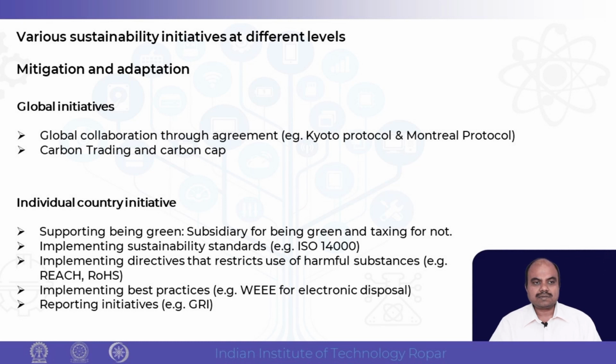So these standards say that ideally these chemicals should not be used, but sometimes that is not possible because of manufacturing limitations. So the standards say that you can use these chemicals, but only up to this amount, per kg or per million, in ppm, depending upon the measurement. These standards restricting the usage of these chemicals are in place by various government organizations. So if you want to sell any electronic product to the European market, your product has to be certified with RoHS certification, REACH certification or WEEE certification, otherwise you cannot sell.